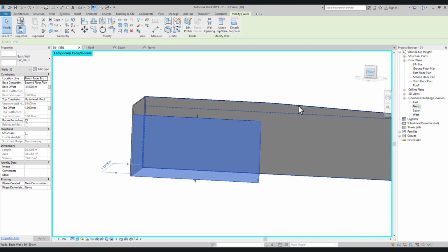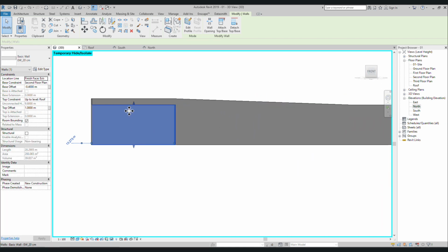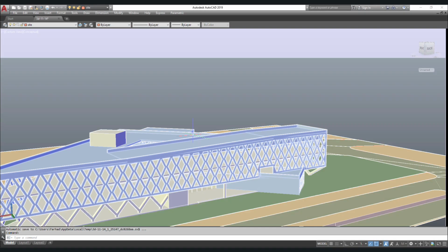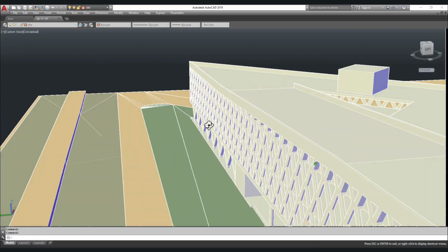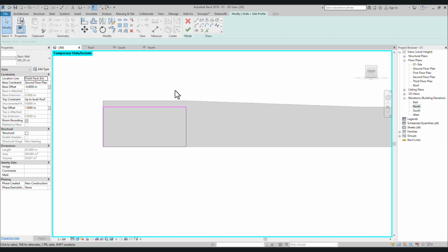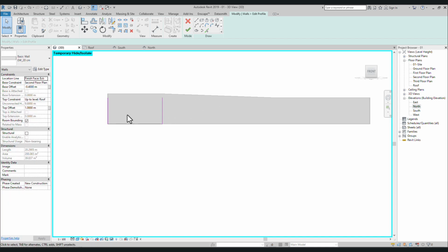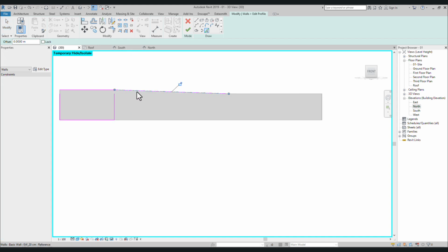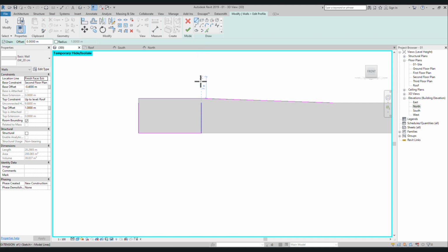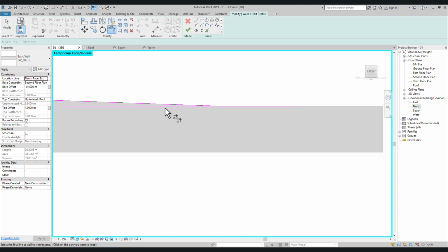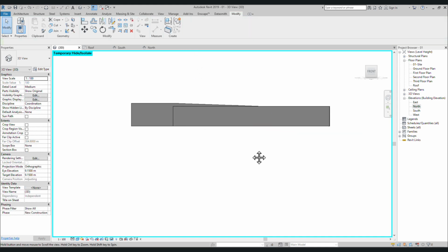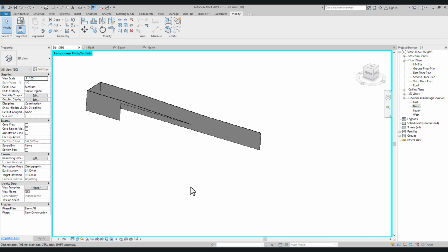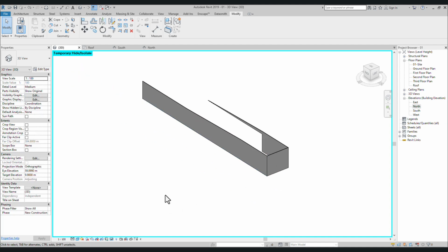And let's also, this one is important because at the back of the wall we have something like this. This wall is based on this wall. It means that they are the same at the top part. So I delete this one. I select pick line, this line, and I select a line from here to here, trim them together, and this with this. That's okay. Now I reset my temporary height and isolate.